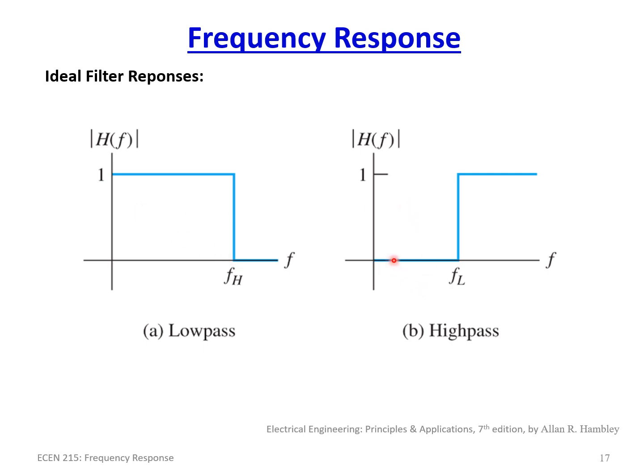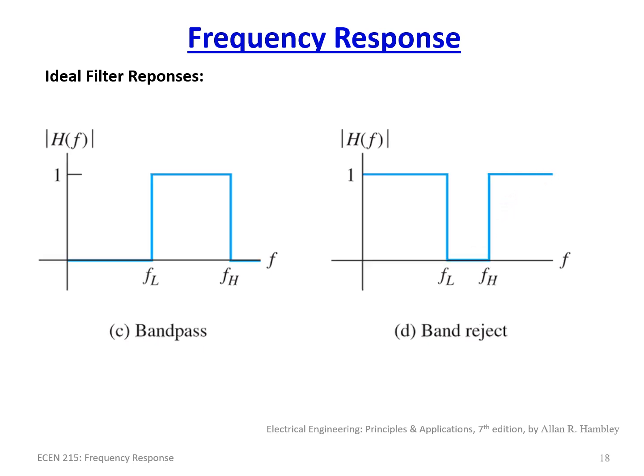High pass filter is the exact opposite of that: we turn on at some low frequency set point, the cut-on frequency, and then from there it is just a magnitude of 1 and will completely pass as needed. Band pass filter has both a low and a high frequency and will cut on and then cut off. Anything below is 0, anything above is 0, and anything between the two is a perfect 1. And band reject, or a notch filter, is the inverse of the band pass, where it passes everything below the low and anything above the high, but anything between the low and high cutoff frequencies is a 0. And that sums everything up.